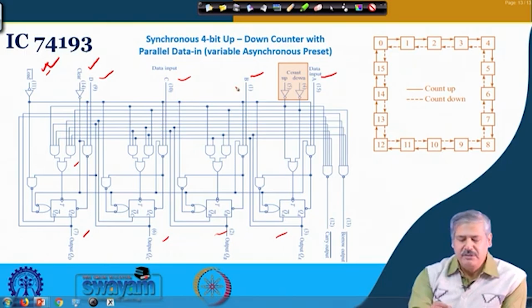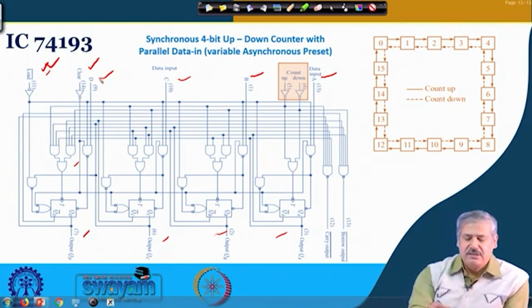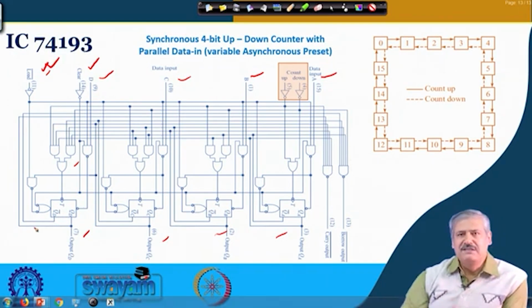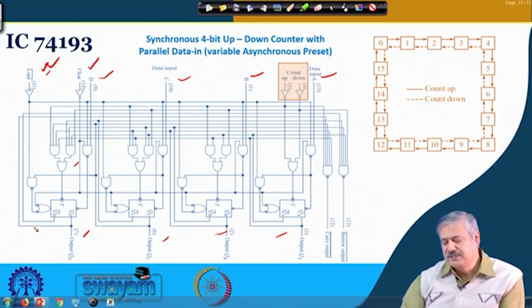So, this is variable because the DCBA value can be different. The idea is if you are putting a 1, then you are presetting it. If you are putting a 0, you are resetting it, clearing the corresponding flip flop. Similarly for the other bits.